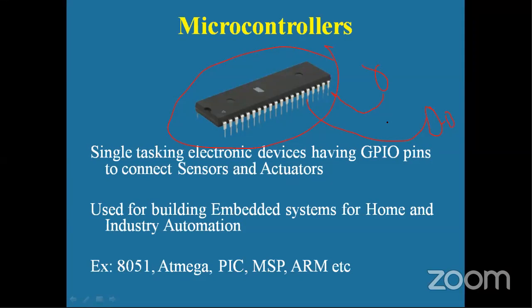Your microcontroller has memory in which you store the program, and at any given time you can store only one program. Then you will say, can we store more programs? Of course, you can write a new program into the microcontroller, but remember that when you write the new program, the previous program will get erased.